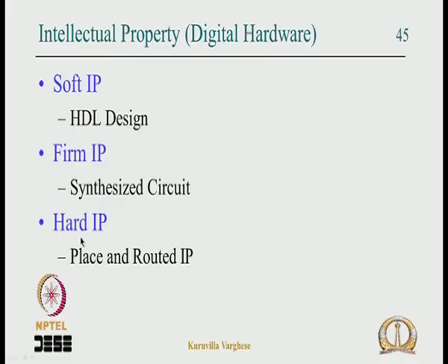The last category is a hard IP, which is literally not just the synthesized circuit, but a placed and routed IP. So you can directly place it in the silicon. The mask is ready for that circuit. So you integrate this hard IP with the other hard IP at the back end tool level.